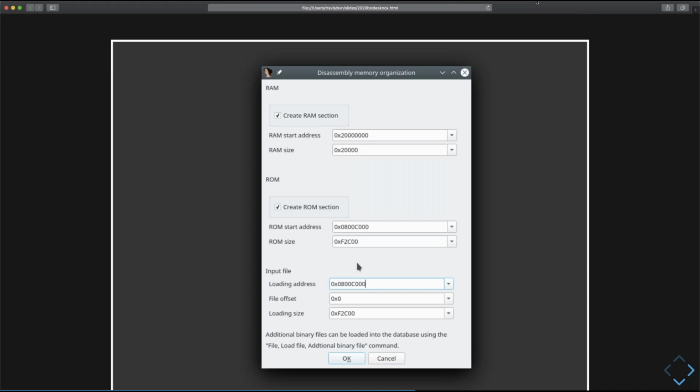And the offset for the second one, I had to find by reading that first bootloader's code. So now that I know that it begins just 48 kilobytes further in memory than the documentation says, I can apply that in IDA and have everything loaded at the correct location.